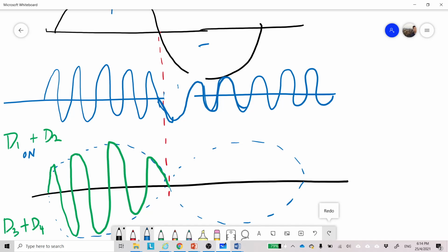You see that the carrier signal goes to the negative cycle, but at that time the modulating signal changes polarity from positive to negative. So during the negative cycle of the carrier, the output will produce positive.